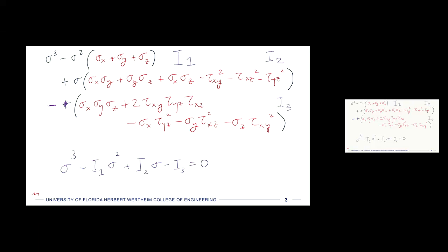Okay, so let's do that for the givens that we have. So all we have are shear stresses. So first I can go through and cross out all of the normal stresses. So I1 becomes 0, right? Because we have no normal stresses. Okay, so that term goes away.